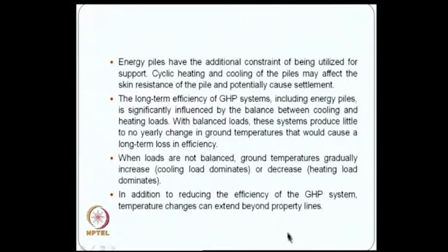So, energy piles have the additional constraint of being utilized for support. This is where the concept of geotechnical engineering comes into the picture, and the cyclic heating and cooling affects the skin resistance of the piles, as just mentioned. Steel pipes are being used, and definitely when you have cooling and heating of the piles, that will affect the skin resistance and may cause some settlements because of this.